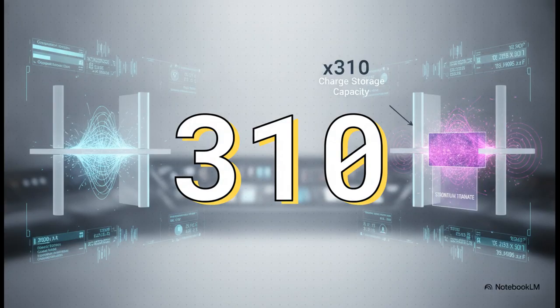To really put this into perspective, let's look at the number 310. That happens to be the dielectric constant of a material called strontium titanate. By simply slipping a piece of strontium titanate between the plates of our capacitor, we instantly multiply its ability to store charge by 310 times. And we do that without changing the physical size of the plates at all. The sheer scale of this upgrade is incredible, but how does slipping a piece of material in there actually work?